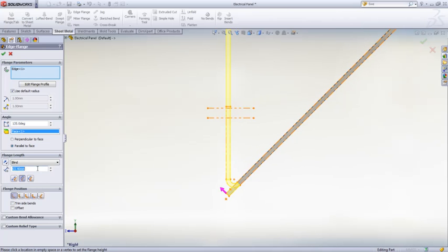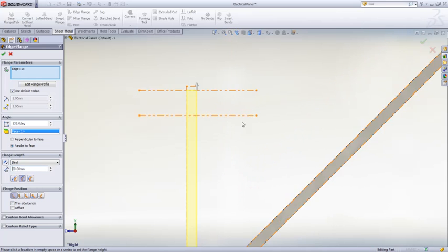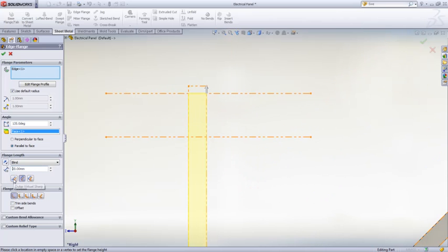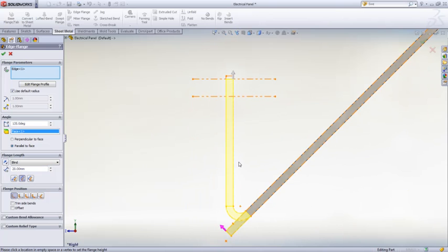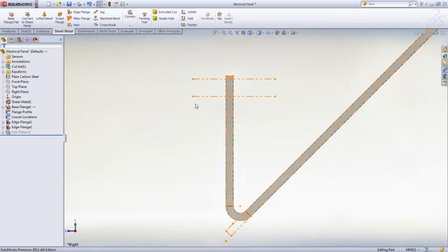Length is another challenge of flanges sometimes. Again, SOLIDWORKS has always had options for outer and inner virtual sharps, but we can see we're not getting the exact 20 millimeter length that we're after. That length is measured from the tangency to the bend to the outside. This way we can simply throw a gauge or a caliper over this to make sure that we have the appropriate length.